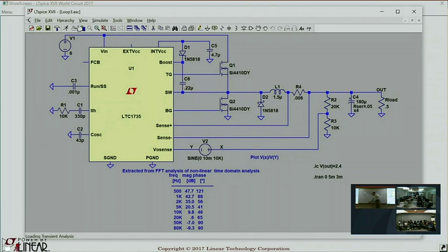See, the amount of slope that you need depends on the duty cycle. Let's make a plot of what slope to use versus duty cycle. So this is slope. That's the slope of this function. M will be the slope, and this will be the duty cycle. That is 100% duty cycle, that's 50% duty cycle. Now, if you're below 50% duty cycle, zero slope's okay, you don't need it. If you're at a high duty cycle, you do need slope.